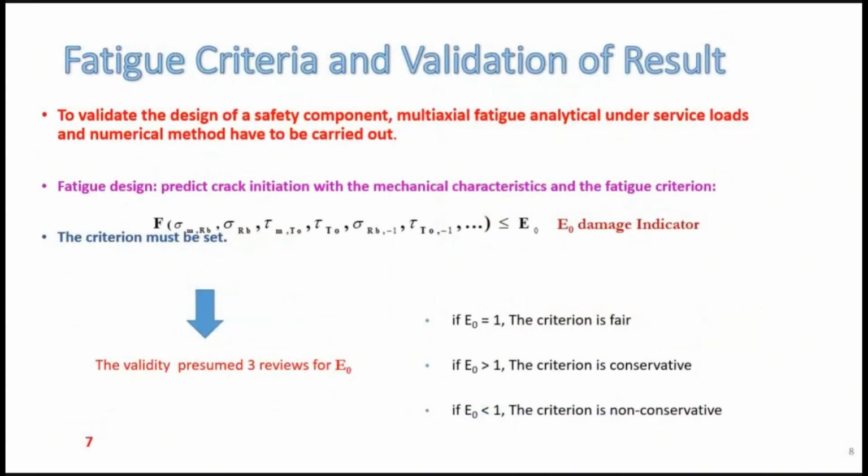Fatigue criteria and validation of results. To validate the design of a safety component, multi-axial fatigue analytical methods under service loads and numerical methods have to be carried out. Fatigue design predicts crack initiation with the mechanical characteristic and the fatigue criterion.